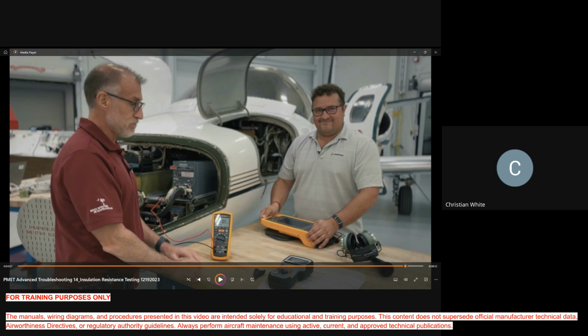What else you got? Hey, so what are the risks with sending that much voltage through a 22 gauge wire versus a 16 gauge wire? Not going to affect it at all. The amperage that you're sending through is going to be about the same as doing a continuity test with a multimeter. It's going to be in a 1 to 5 milliamp range. So it's not the amperage. You're just hyping up the voltage really high so that it jumps. Again, we don't want to shoot through boxes, but it's not going to hurt wiring at all.